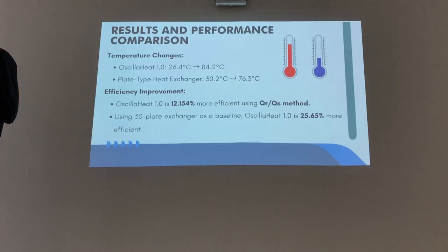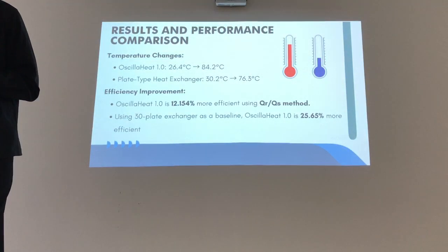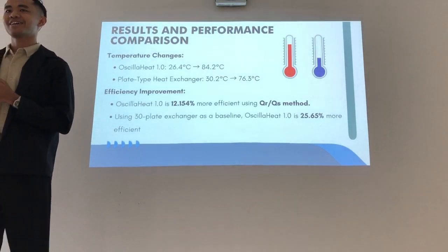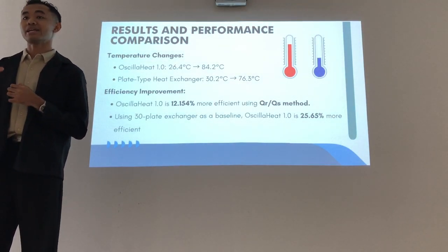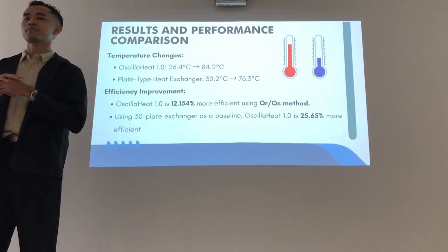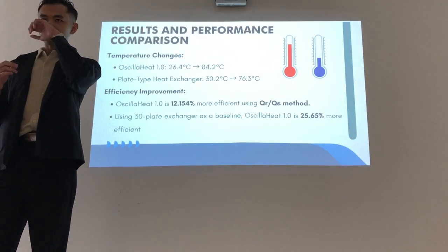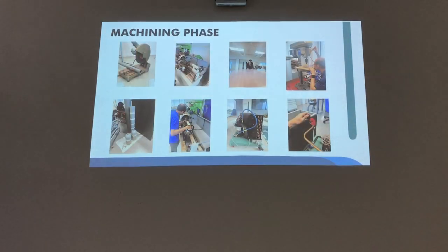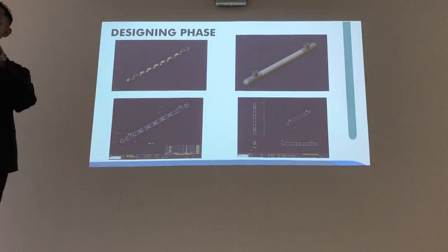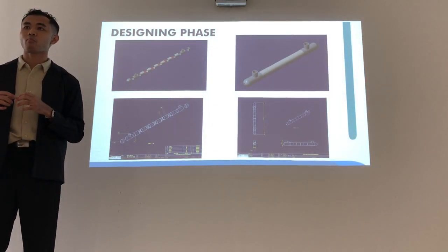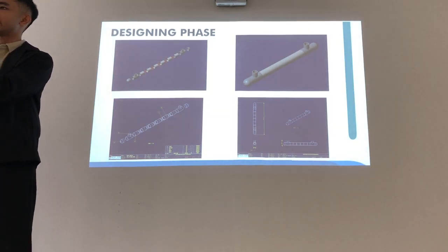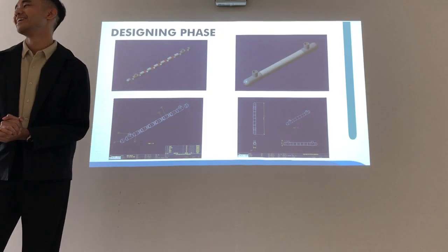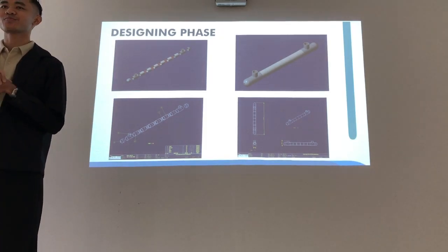What I couldn't visualize is how the heat exchange is done between your copper pipe and your PVC pipe. It's definitely not laminar flow. How do you cause the turbulence there? You could probably flow in a zigzag pattern, so it moves back and forth. There is some kind of movement, so the boundary layer is disrupted. To see how you observe the boundary layers, you can do a CFD.